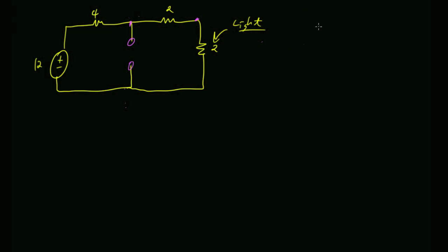Well, let's see. So what's my total impedance that is seen by the supply? I just add those together, right? 4 plus 2 plus 2 is 8. So the total current that's being drawn is 12/8. What is that, 1.5? Is that really 1.5? Yeah. Okay. So 1.5 amps is going to come out of here.